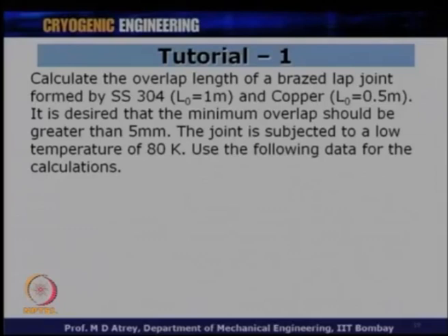The statement also says that the overlap of these two materials should be greater than 5 millimeter at low temperature, because the shrinkage would happen at low temperature and the overlap will decrease at low temperature. And therefore, what should be the overlap at room temperature? In effect, that is basically the question.